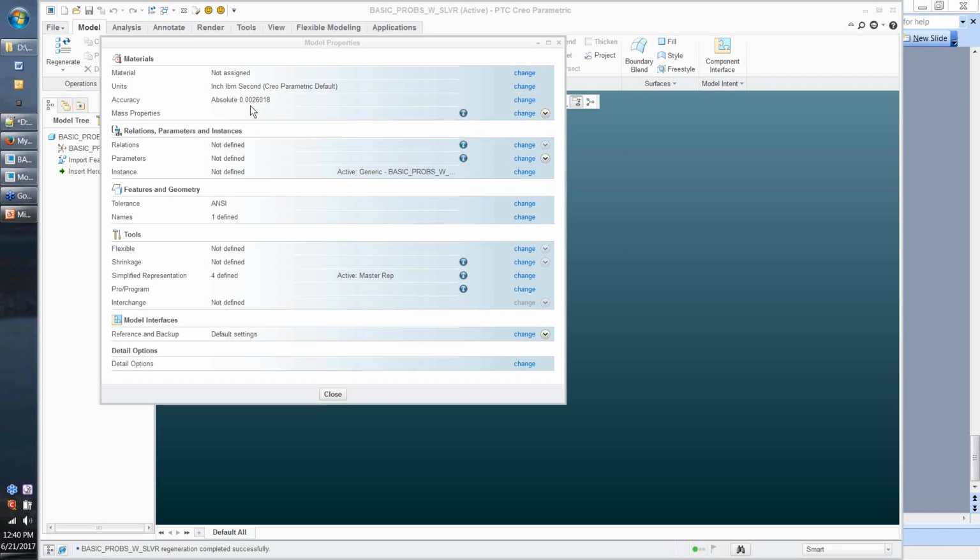And moving forward, I would only change that accuracy in a way that increases this number. Under no circumstances would I ever make an attempt to decrease that number, because it's very likely to result in enormous problems with the import file having far more open edges that I now have to go back and repair, or other problems that will occur when PTC tries to declare a piece of topology and rewrite it onto your screen that was never that good to begin with.